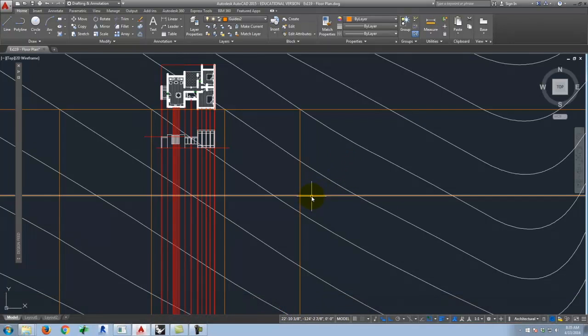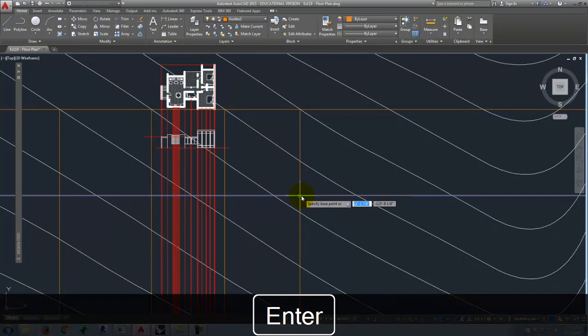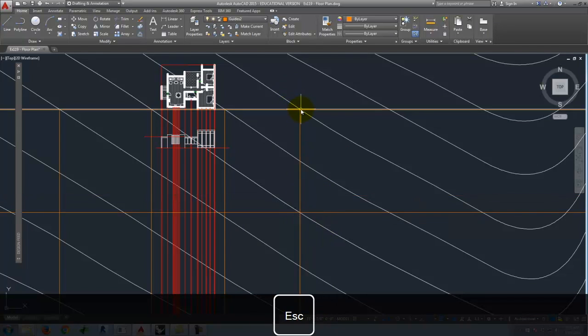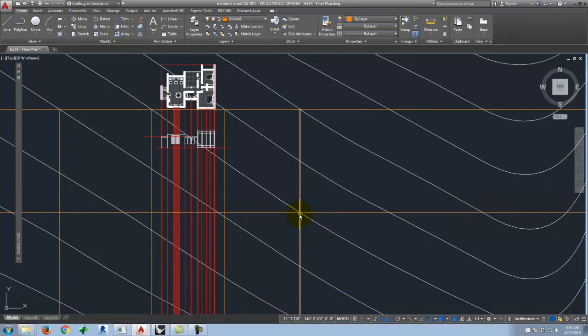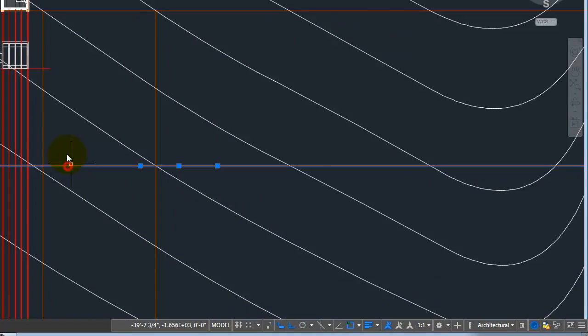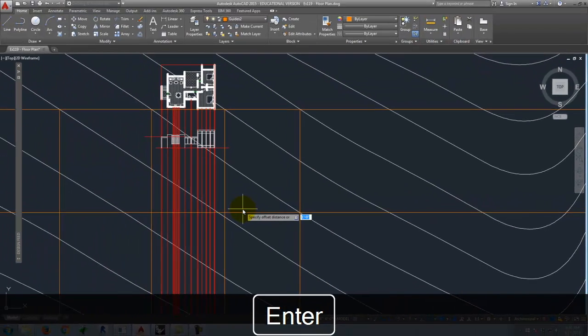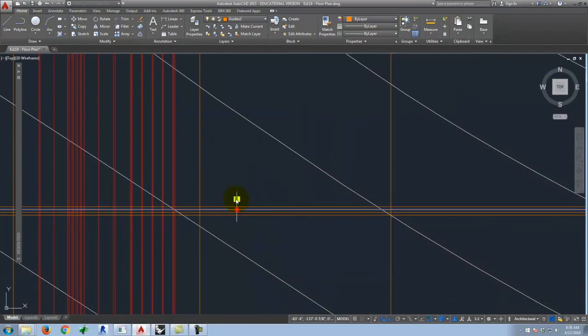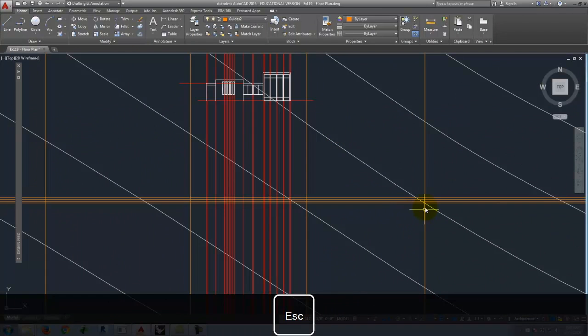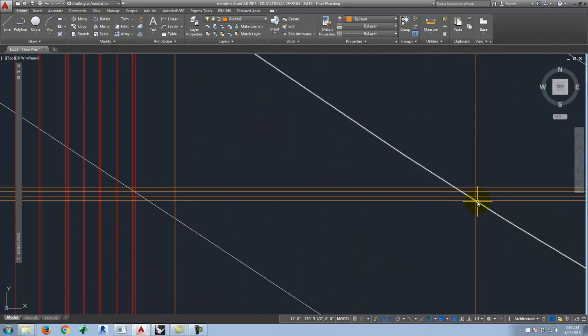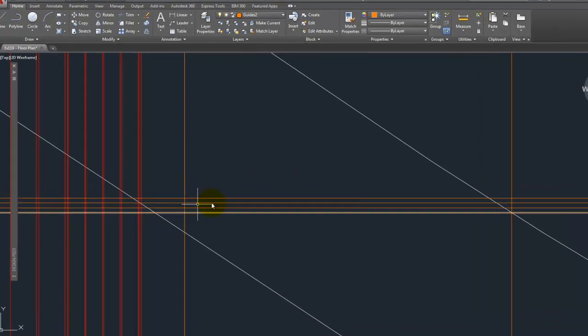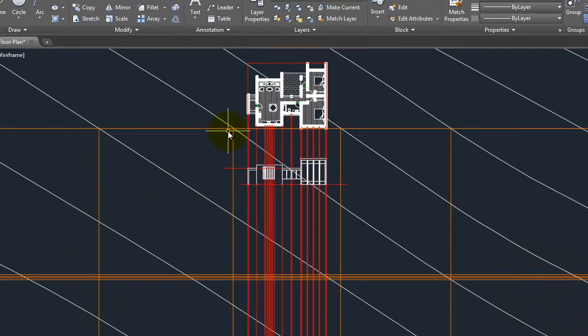Okay? Well, actually, let's make this a little bit easier. If I come to this point and I start with a construction line here, each of the contours is at a 1 foot interval. So at each point that I cross these next 3 lines, it's going to be up 1 foot. So I'll take this line and I'm going to offset it by 1 foot, and we'll go up 2, 3, like that. And so now I can draw a line that starts at this intersection and moves up at each subsequent point that goes along here.